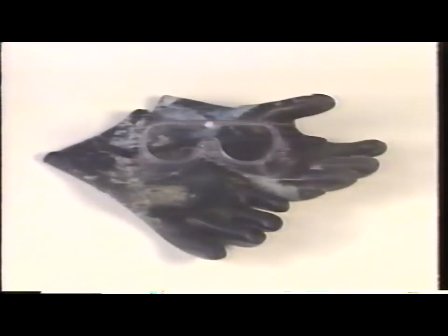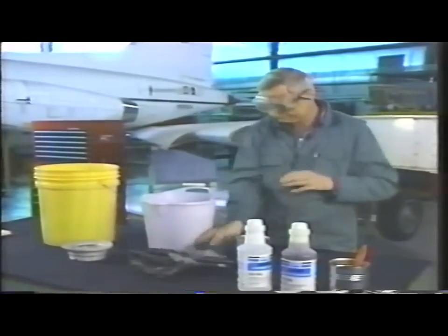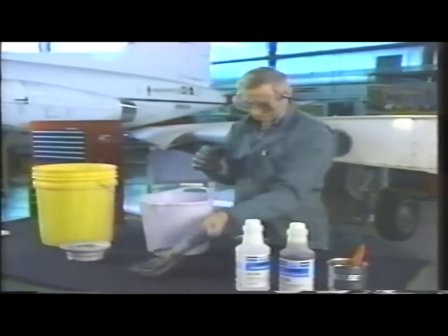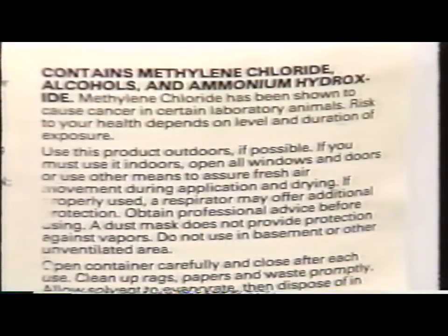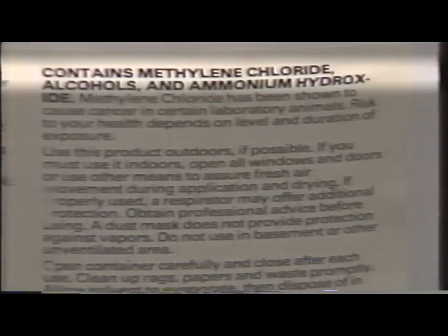Whenever you are working with chemical paint removers, check the label or material safety data sheet for any special manufacturer's instructions you may have to follow. Wear protective goggles and rubber gloves and protect your skin from accidental splashes. Do not use chemicals of any sort in small, unventilated areas, and always wear a respirator when directed by the manufacturer's instructions. Do not use paint removers containing acid on aircraft surfaces. Instead, use phenolic and non-phenolic paint removers.